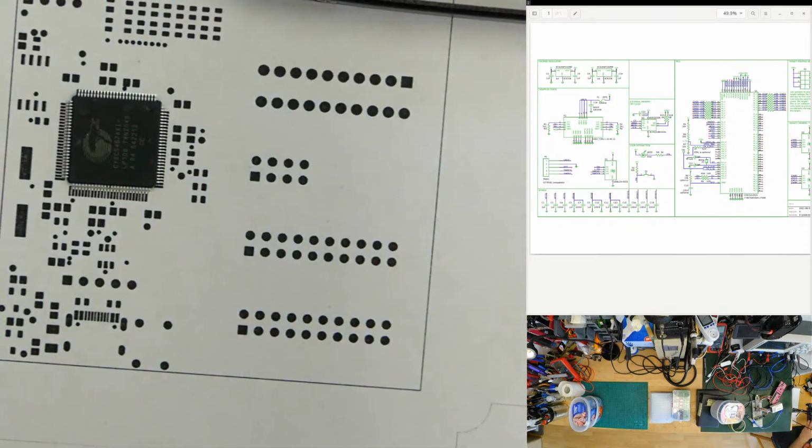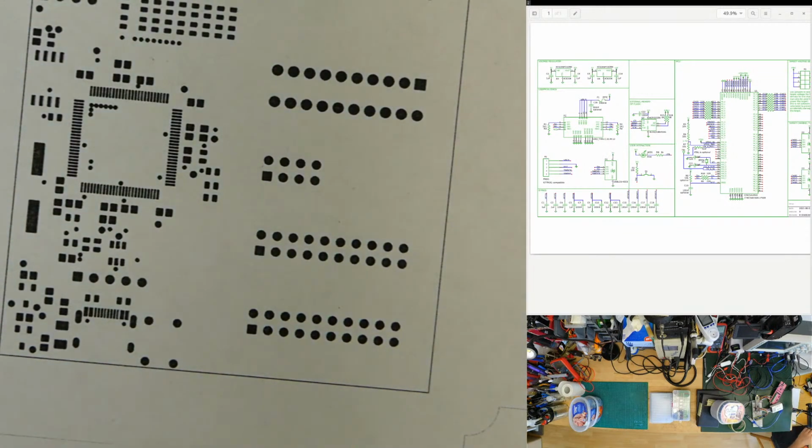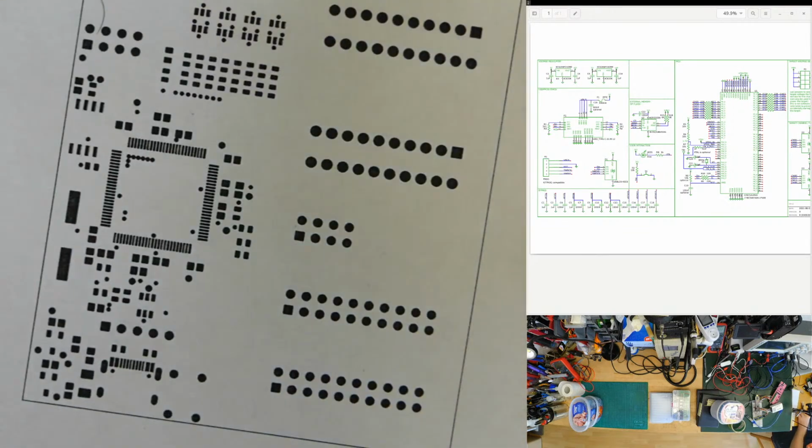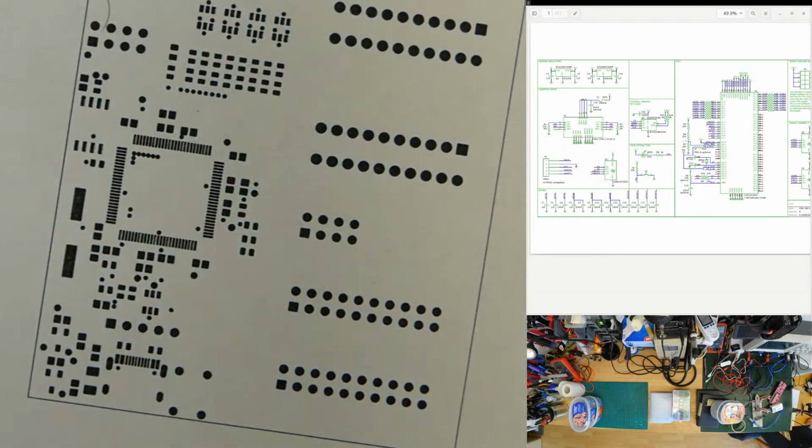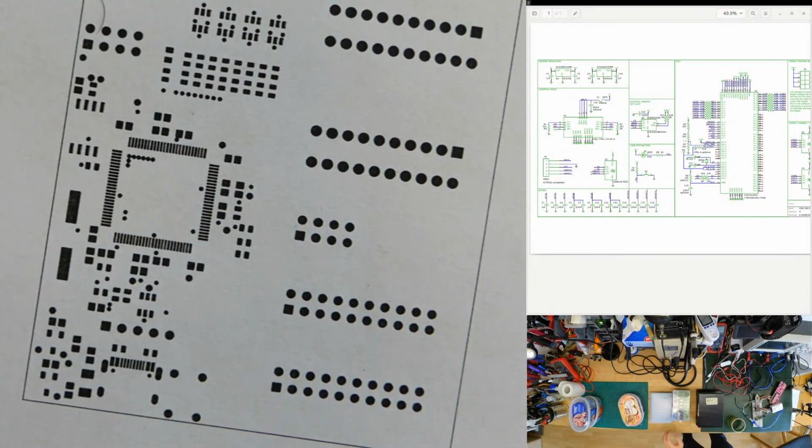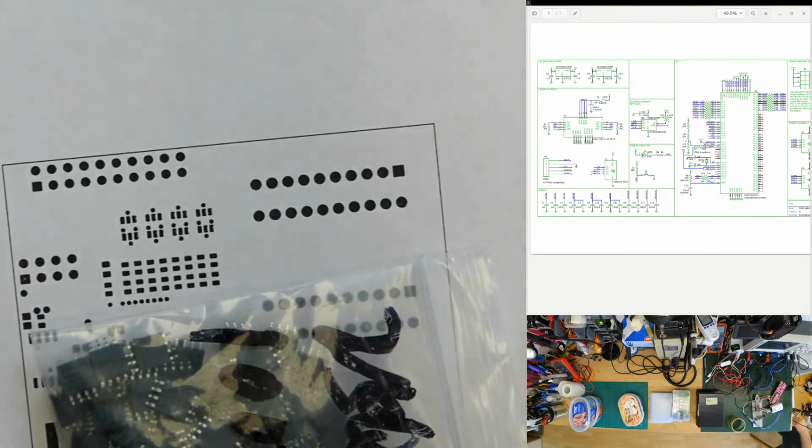And with all of that, all the rest are capacitors. No, there's the SPI flash. I've never used SPI flash, and I have to pay attention because for SPI flash you have tons of different packages. Normal body width, large body width, and so on. So the microcontroller goes here, and the SPI flash should be here. I have a bag full of them. Yeah, SPI flash costs nothing nowadays.